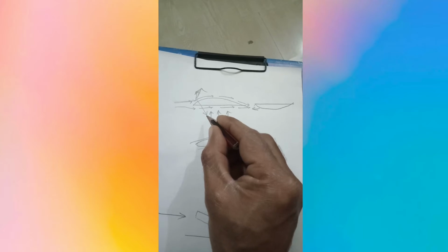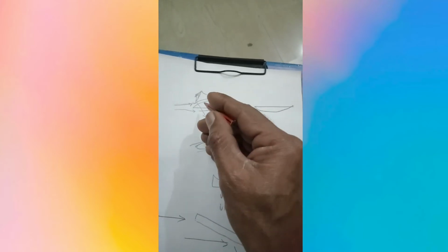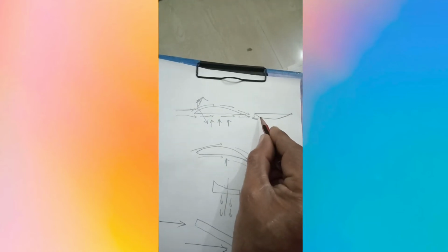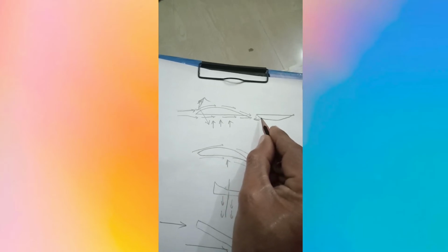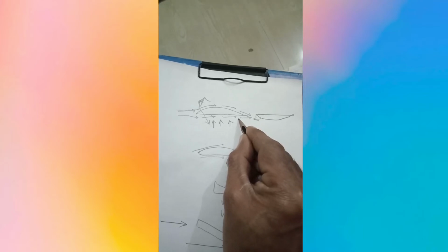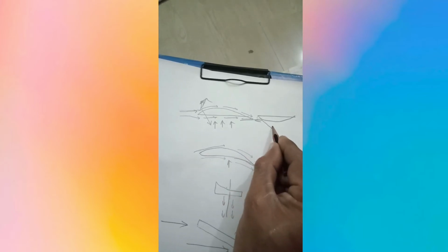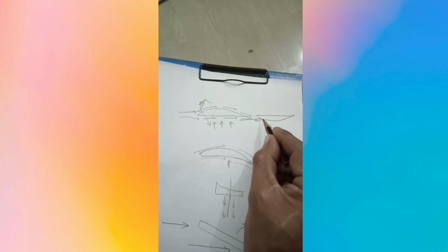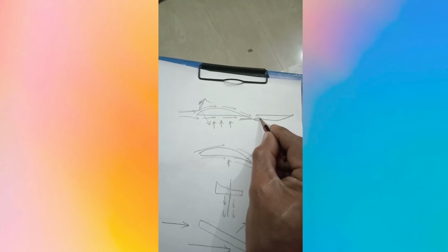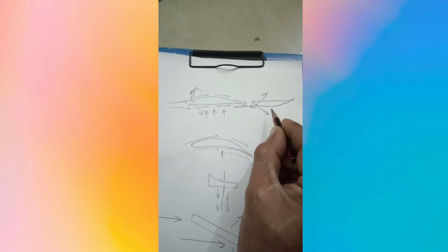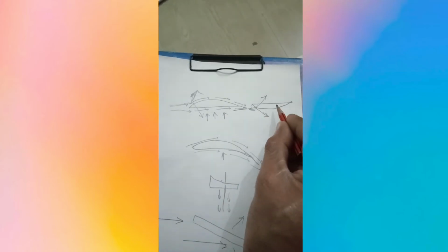So if this is giving it a downward push, if you reverse it, if you turn the wing upside down and give it this sort of shape, let us try to see what should happen. If it is moving in this direction, the wind will be striking in this direction, and the wind will be moving downside. When the wind is moving downside, it will give a push according to Newton's law in the opposite direction, that is, it should be giving a push towards the upside. So it seemed that if this shape was not working, this shape should work.